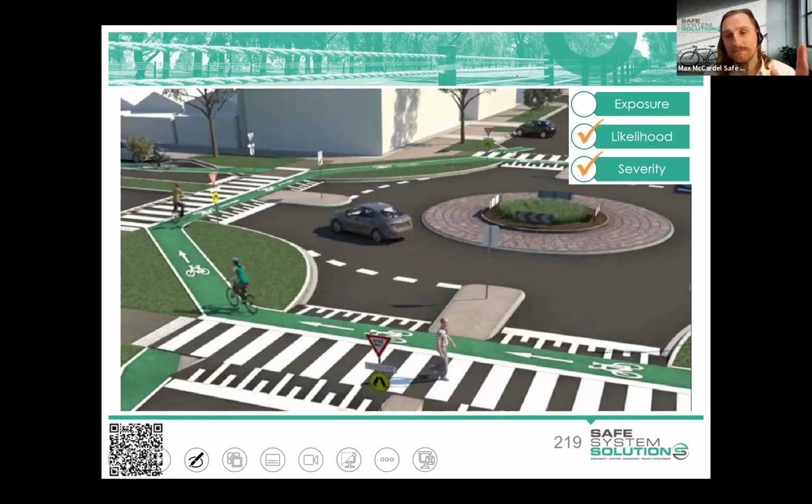And at the core of it, what is occurring is we want to get bike riders out of the circulating area. As soon as they enter that space, they can either get pushed to the periphery, or drivers that are entering the roundabout will just fail to give way to them, fail to see them, and you just enter the roundabout and there's a collision there. There's a host of reasons why it's not a good idea to have riders within the circulating area, unless it's very, very low speed and local streets and stuff like that.